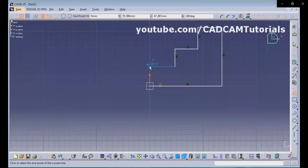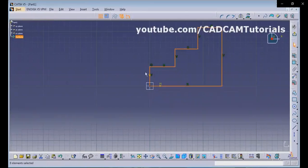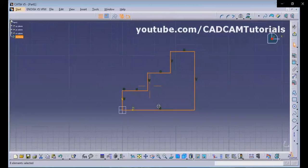It will automatically track when you are in line with the V-axis, and it will automatically stop when you close it. Then click outside, then go to constraint, click on this constraint location.